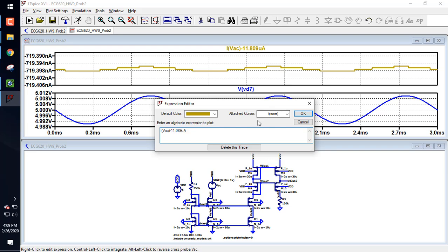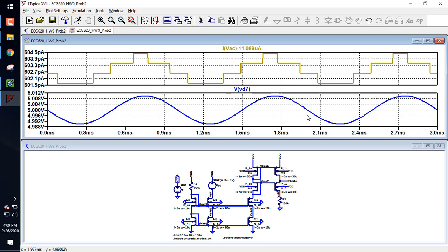You see how that's got the jagged shape, right? The reason that's there is because of numerical simulation issues. So in a SPICE simulation, it says to itself, when I get below a certain level, I'm going to say that the simulation's converged, and I'm going to move to the next point. I'm going to show you how to fix that.